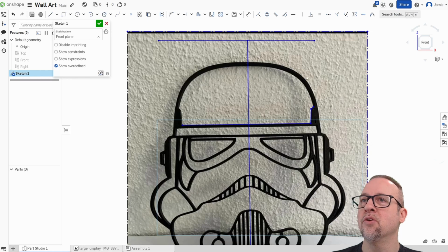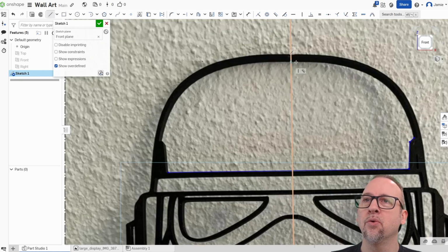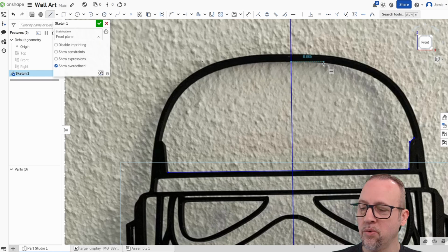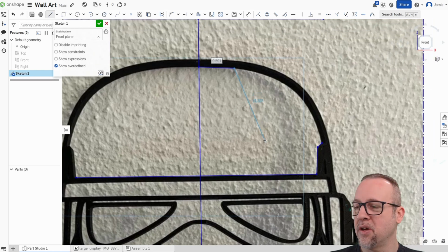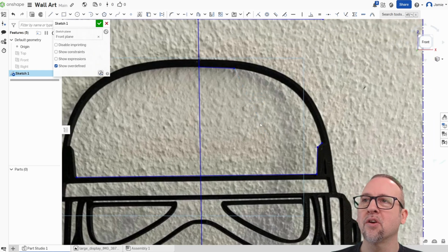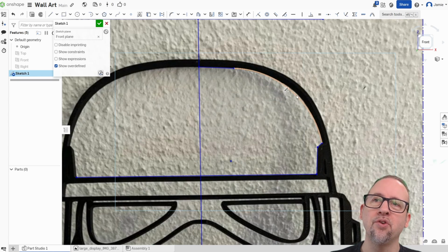So let's create this curve right here. We get a little flat, so let's create a little flat. So we go here to here, shift key, remember, shift lets us go to whatever we want and allows us to click that. Okay, I'm going to right click, end this guy, escape the line. I'm going to build a tangent arc from here to here, and it already snapped to it. So if I don't like that, you see it's got a little bit of gap there, I can undo, Control Z to undo that.